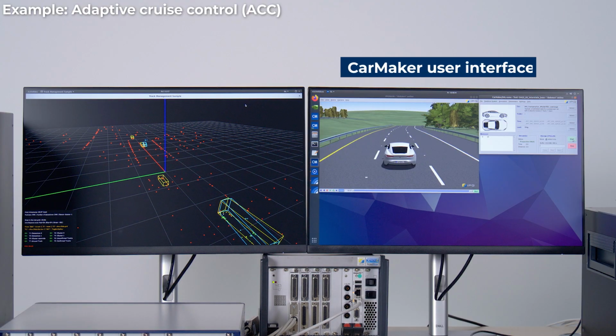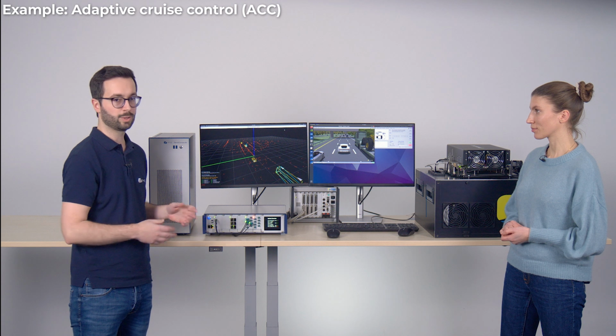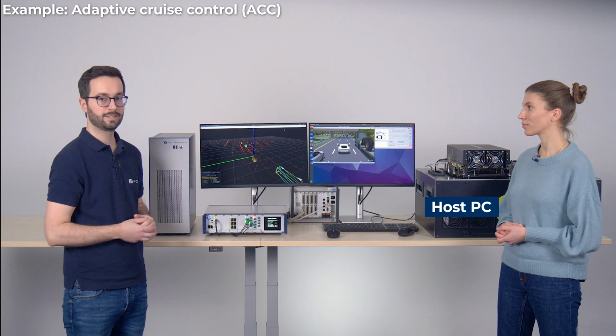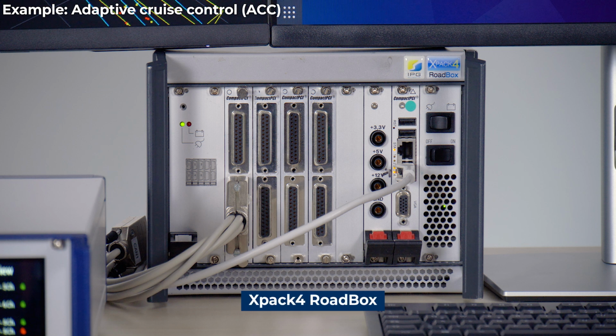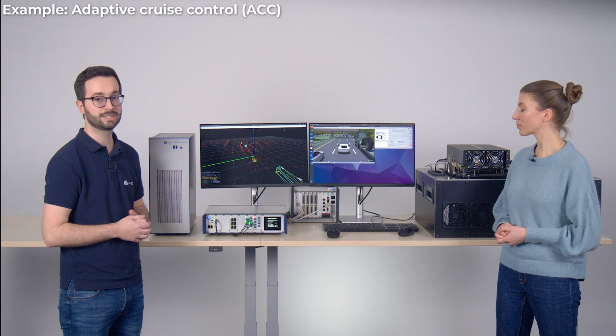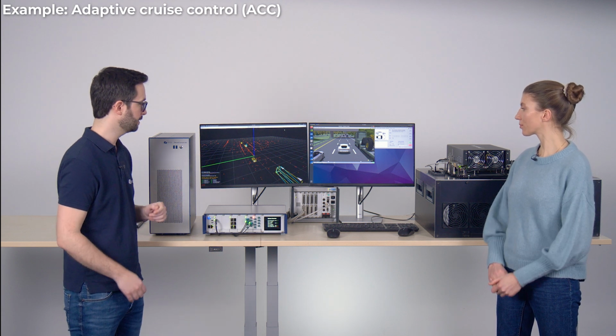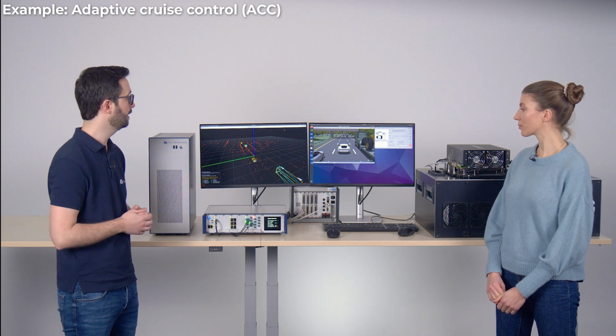On the right side we see the CarMaker user interface together with a visualization of our test scenario. The user interface is running on the host PC inside the black box. And this one is connected to our XPAC4 road box where the actual scenario simulation happens, and also the vehicle dynamics simulation and the I/O generation for our system under test, so CAN communication basically.